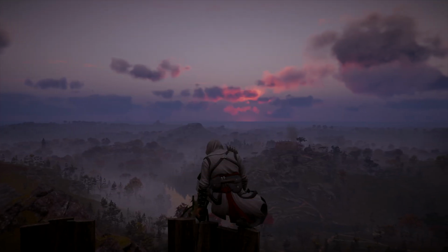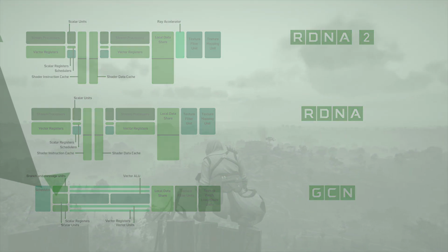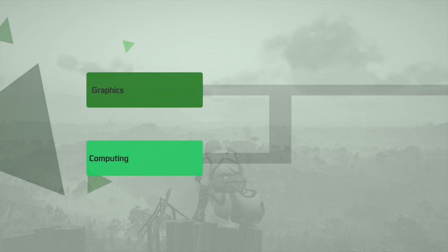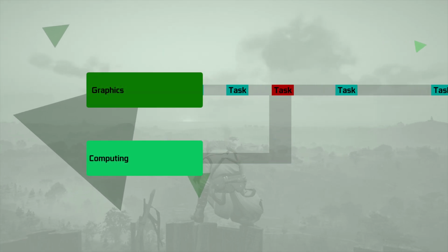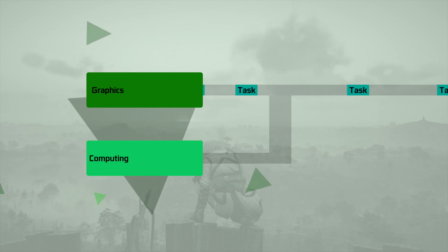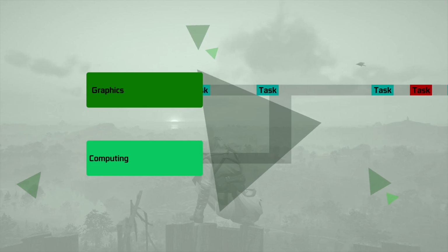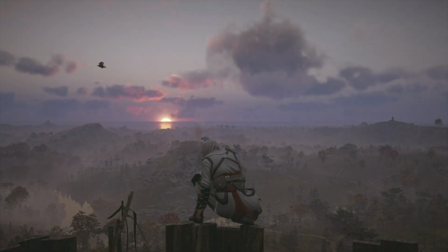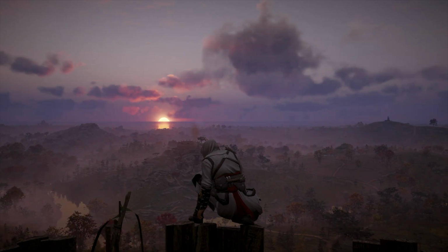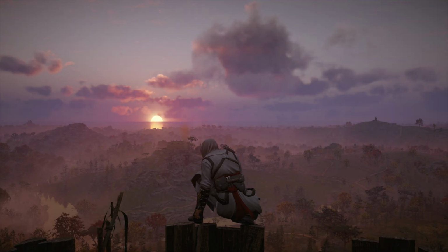At first glance, RDNA 1 and 2 compute units have a lot in common, and we will come back to that later. AMD continuously uses their approach to async computing with 4 async engines. It helps to manage the priority levels for graphics and computing tasks, since computing tasks can be pretty latency sensitive. This design was used at first even in Radeon HD 7000 cards. However, it was so broken back in the days that for now the HD 7000 series has the system shut down on the driver level.